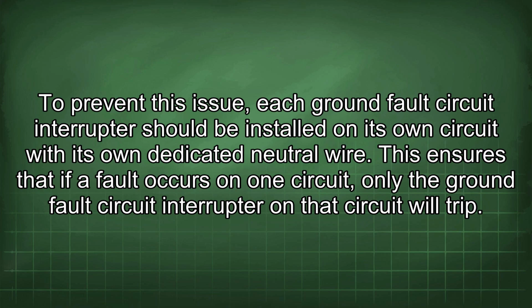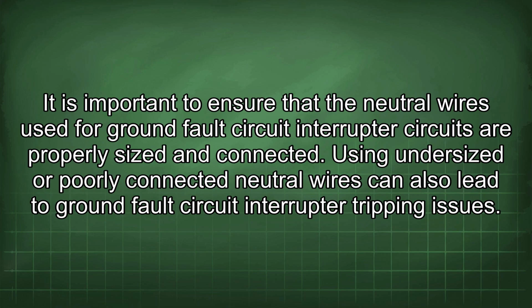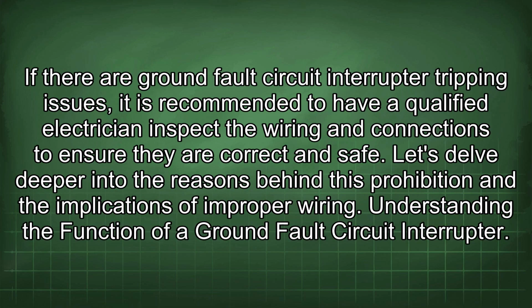It is important to ensure that the neutral wires used for ground fault circuit interrupter circuits are properly sized and connected. Using undersized or poorly connected neutral wires can also lead to ground fault circuit interrupter tripping issues. If there are tripping issues, it is recommended to have a qualified electrician inspect the wiring and connections to ensure they are correct and safe. Let's delve deeper into the reasons behind this prohibition and the implications of improper wiring.